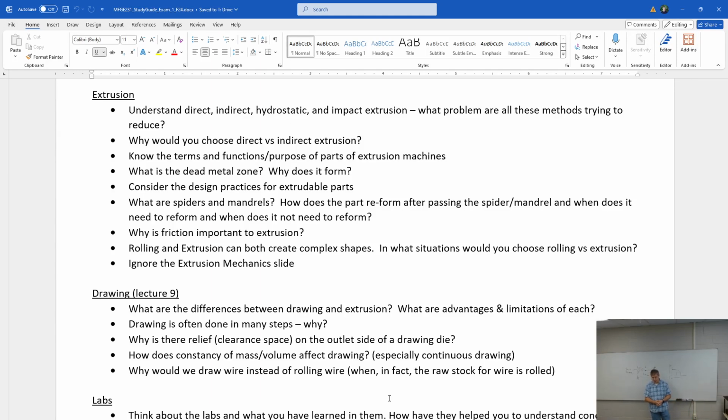Well, it's a thing called superplasticity. So if you do a process fast enough, you can cause, within the structure of the material, localized heating and localized softening, which allows it to deform superplastically, but it does not heat the part overall too much as a whole, and so it won't change the properties of the part very much. It's pretty neat.